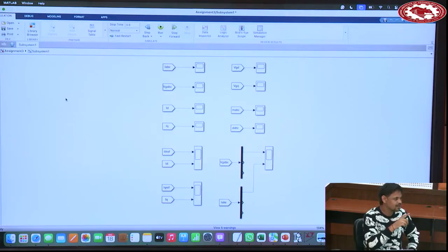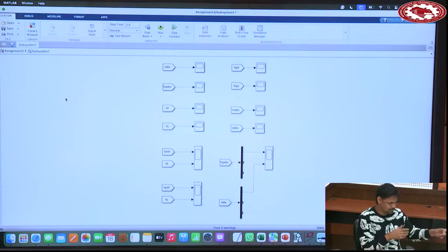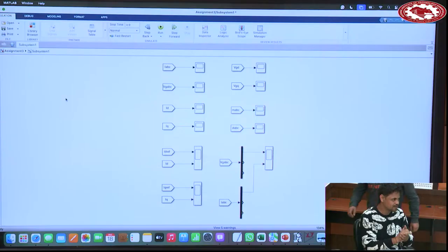And the fourth condition to go into overmodulation is reactive power. You have designed your DC link according to active power sharing. When reactive power comes into the picture, it requires more DC link. So if you are feeding reactive power, then you need more DC link.